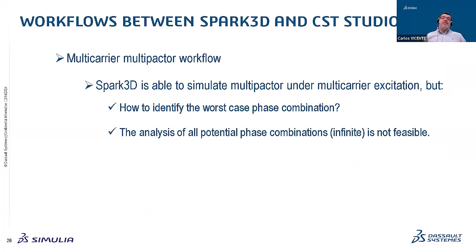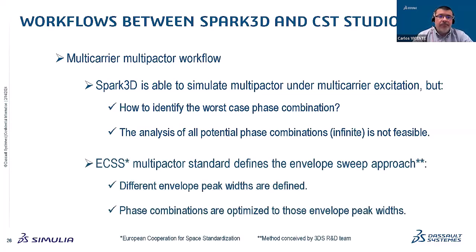And of course, you have infinite potential phase combinations. Therefore, we have a problem here, because Spark 3D can analyze anything, but you cannot spend ages analyzing all possible phase combinations. So this is where the European standard for multipactor is really helping us.